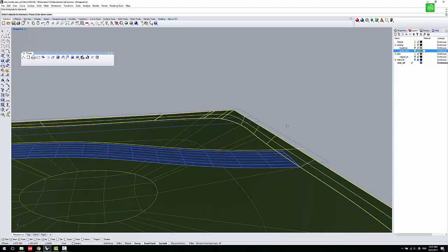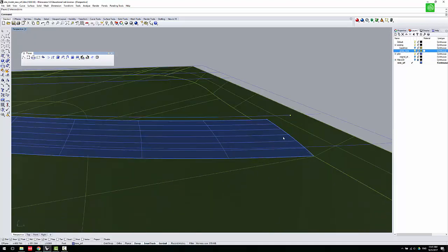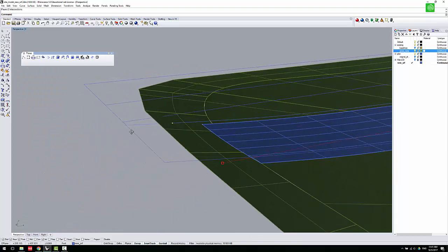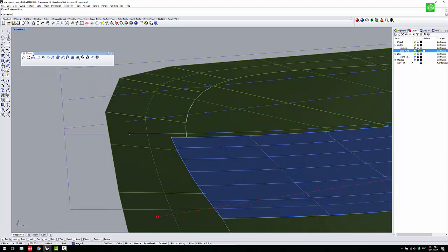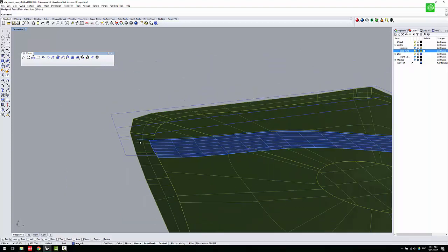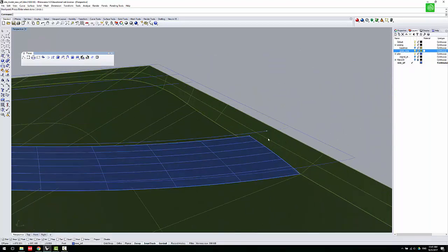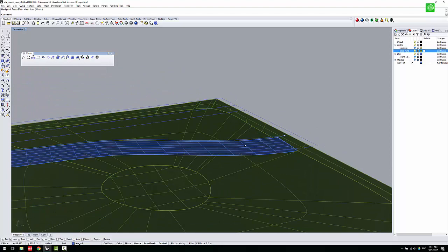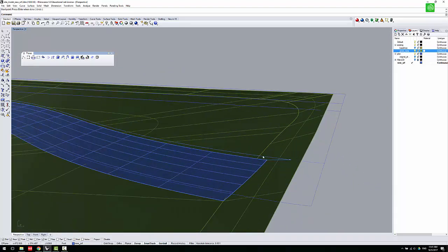Click the surface, hit enter. So they will find the points again. Okay. So we have the points, which is the key. And then what we do is very easy. We just interpolate on surface and just draw the curves on here. The same with here, interpolate on surface, draw from here. Okay. So then we have all the same with this line.